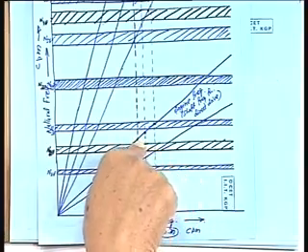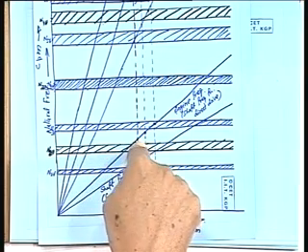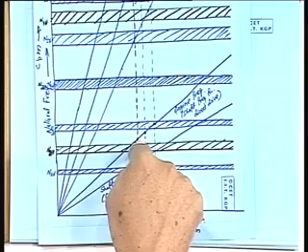Okay. So, if you try to cut down the MCR, what I am trying to say is that the engine RPM we are talking about is whatever the operating RPM is. If you are designing a vessel to operate at 80% or 85% MCR, then this is the 85% MCR RPM.